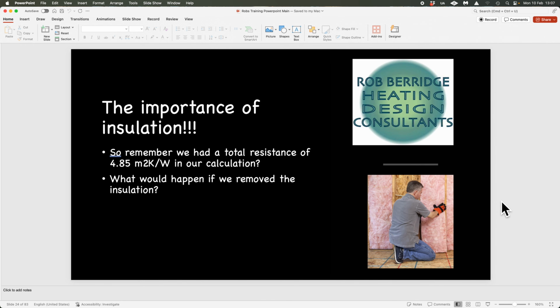So I would always suggest, whenever you go in to do any work or penetrations into any wall or construction of any building, I have a little selfie stick which I put on the end of my mobile phone, and I will get up into the loft space of each building and I will check. I'll also look on the outside and see if there's been any drill holes or anything where it might have had phenolic foam pumped into the building. But speak to the clients, find out what the wall makeups are, but get up into the loft spaces. Put your phone on your selfie stick, put it on video, and put the light on, and just poke your video down into the eaves of the construction, and you can have a quick look down the cavity to see what it is.